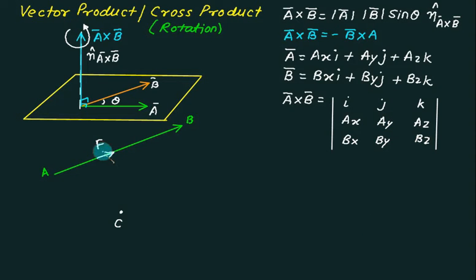Consider the moment, which is defined as force multiplied by perpendicular distance. So the moment of the force about C is defined as force multiplied by the shortest distance. Will this force about this point rotate clockwise? So your sign convention is this. Basically this is a vector quantity because it has a magnitude and a direction. The shortest distance is the perpendicular dropped from C, so this smallest distance is the distance between F and C.